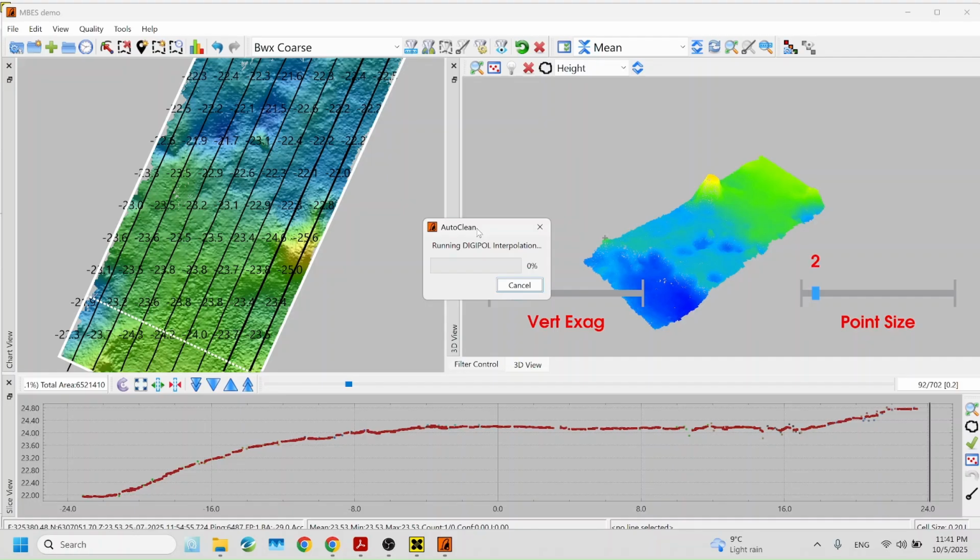In this video, we imported our data, set the correct coordinate reference system for the survey location, and applied the vehicle profile we obtained using the patch test. We checked that the data shows up in the correct location on the map, and performed some basic cleanup. Now we are interpolating the data to fill the small gaps that are always present in every correctly planned survey in a natural environment.